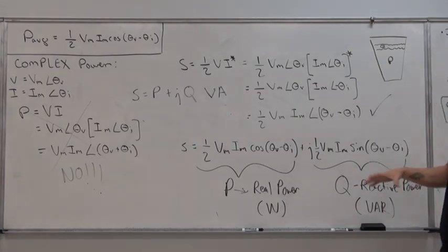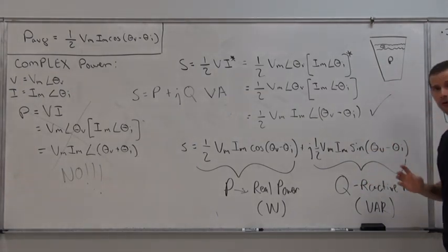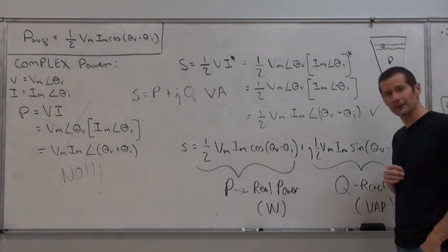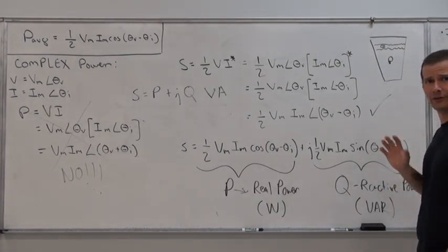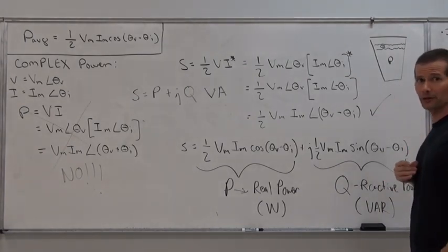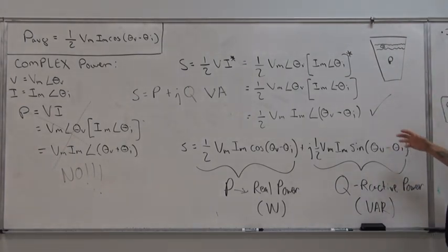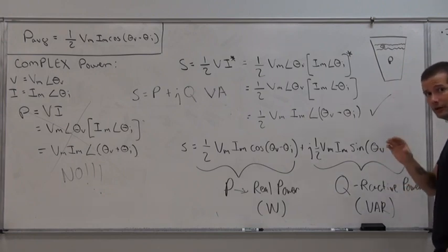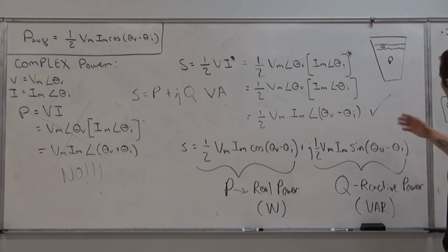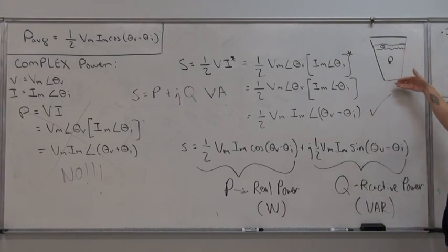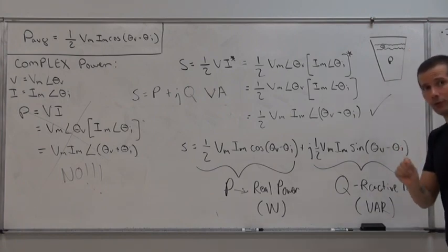If we look at the total power within the system, volt amperes, it is basically what my old mentor, Dr. Haskell, introduced to us in a very simplistic way: a glass of beer. So if we have a glass of beer here, and we fill it up, what does the foam represent, and what does the real beer represent? Well, if the total power within the system is representative of that glass of beer, then the real power is the beer that we actually like to drink. And the reactive power is essentially that foam on top.